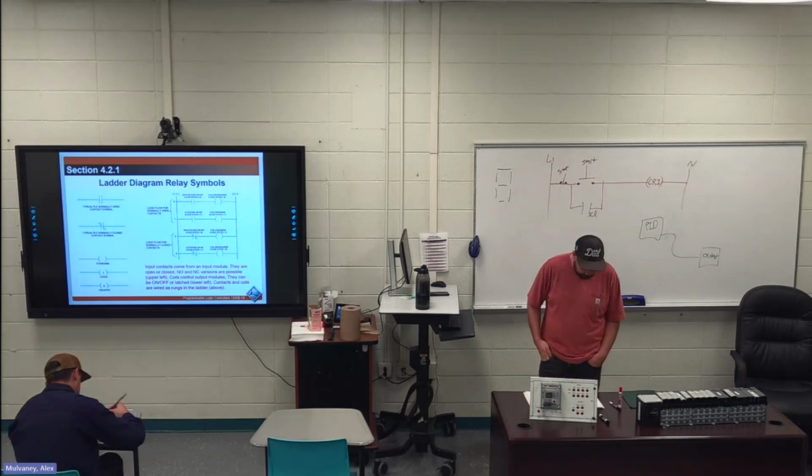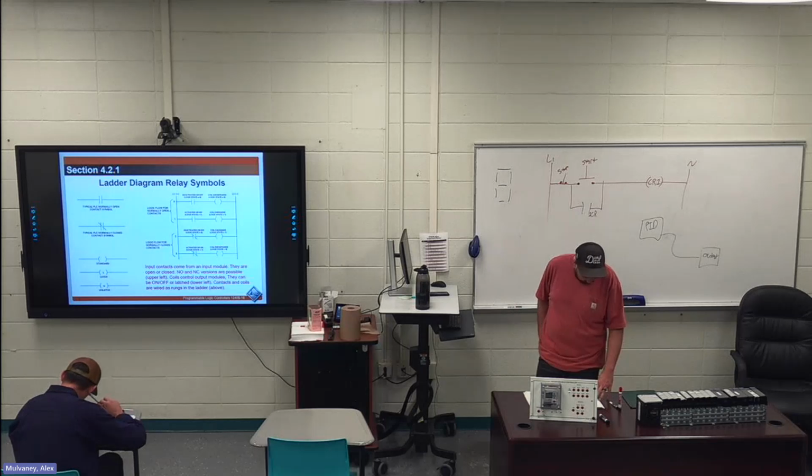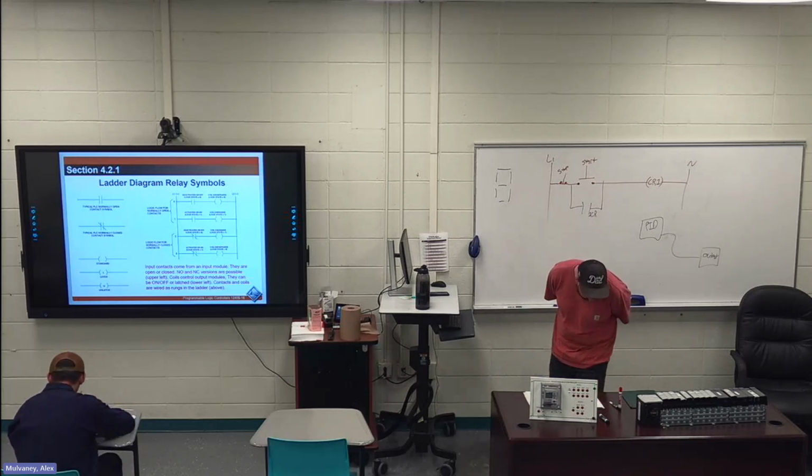Data comparison 424. This would be like the if-then statements. Second paragraph in 424 on page 26, first sentence is highlighted. In the ladder language, there are 3 basic data comparison instructions. You have equal to, greater than, and less than.